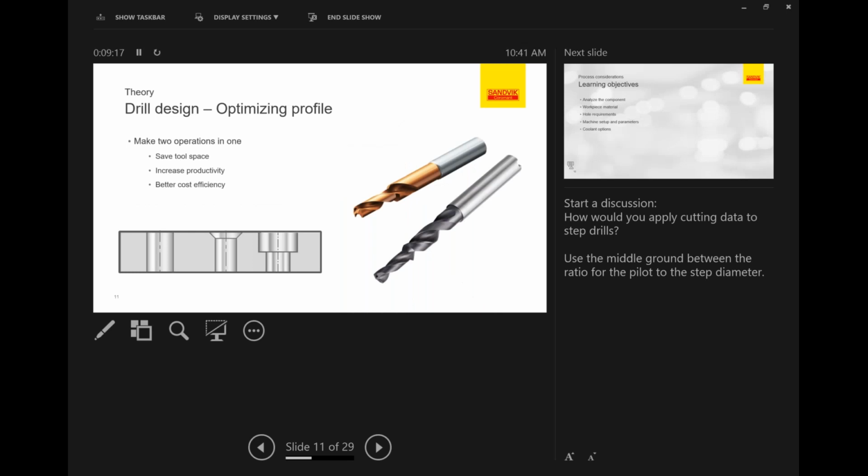As well, if you are drilling and chamfering, or drilling and counterboring, we have a tailor-made option where we can design a tool that fits your need, so it's all one shot. We also offer drill chamfer tools that correspond with tap drill sizes, so you already have a drill chamfer tool available that corresponds with tap drill sizes.